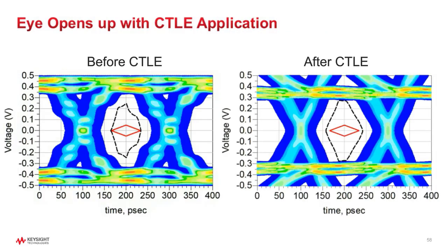Thank you. Great. Here's a question from Sarush about the simulation of the differential T-line. What ports do we need to use in ADS, and what is the characteristic impedance? Is it odd mode or even mode? Well, Sarush, the port we need to use is none, because the solver I use is a 2D field solver, and it will give you a very quick, accurate answer, given your 2D cross-section. But if you're asking about the 3D solver, then that is different, and we can talk about that offline.